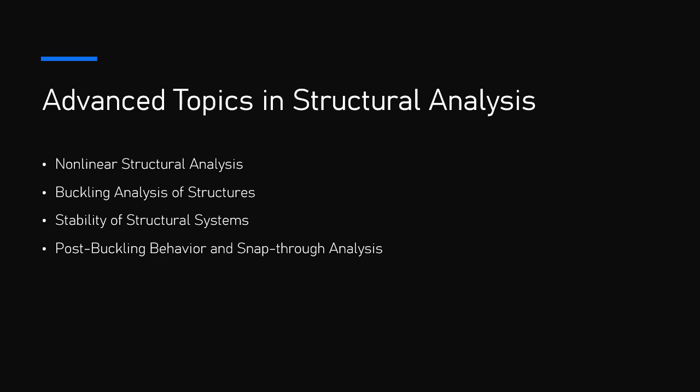The post-buckling region typically involves large, nonlinear deformations, and the structure's ability to carry additional loads may change drastically compared to its pre-buckling behavior. 1. Types of post-buckling behavior. Stable post-buckling. In this case, after buckling, the structure undergoes large displacements, but the load-carrying capacity increases or remains relatively constant as deformation progresses. Stable post-buckling behavior is seen in certain thin-walled structures like columns or plates.